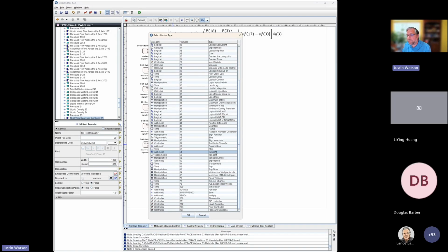There's square root, there's subtract, there's step, there's no square. So there's a couple different ways that you can square a value. We could create a whole other copy of that signal variable and multiply those two signal variables together, or we can just multiply the same signal times itself, and that's what we're going to do.